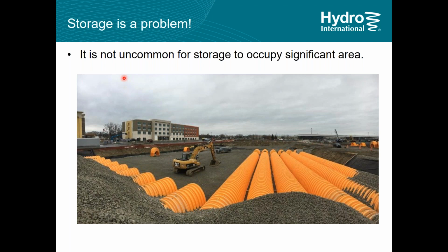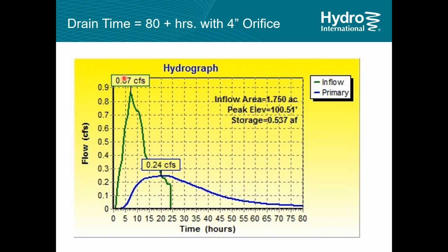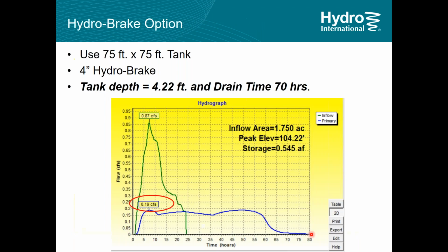So can we use the vortex valve to solve this problem? And certainly you can. So one of the things to look at also is drain time. With the previous design, the drain time is very long as well. We're looking at 80 plus hours. So your cycle time on the tank is a consideration as well.